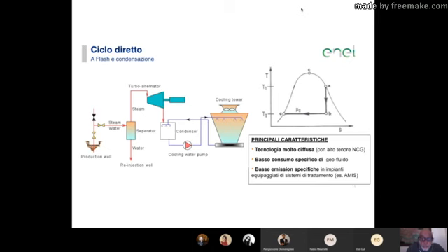Now in Tuscany, the fluids have a very large amount of non-condensable gases, so this is about the only technology that you can use at the moment. Because the non-condensable gases, you have to throw them directly to the atmosphere, otherwise they clog up your system, and you're not going to be able to produce electricity anymore, because the pressure in the condenser is not low enough.